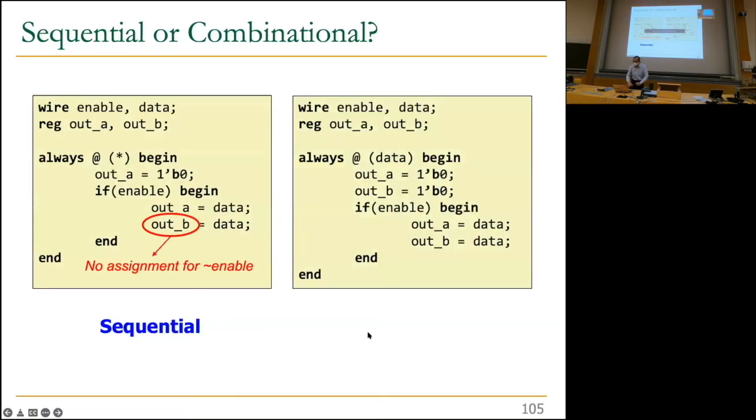The second one, is this combinational or sequential? Any takers? Yes. Exactly, yes. This is sequential because this doesn't get executed when enable changes.